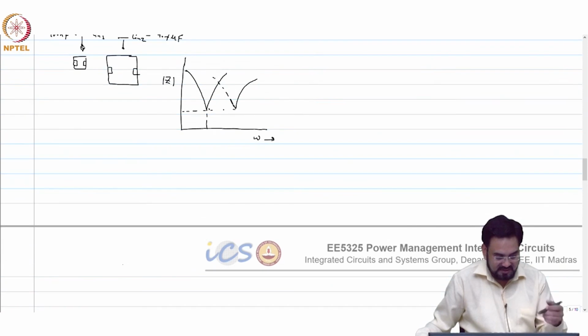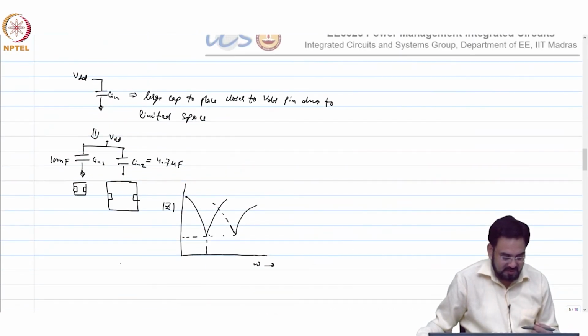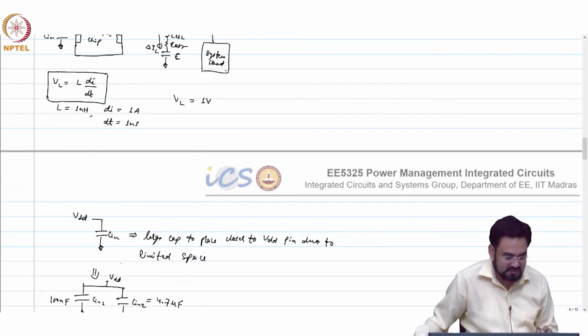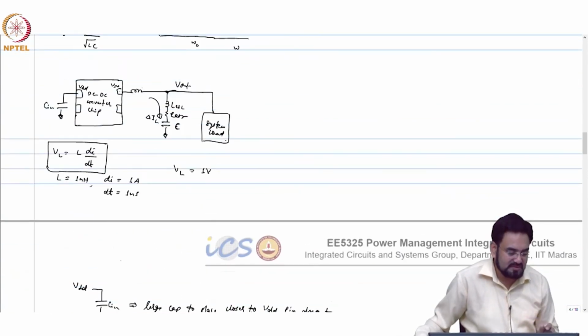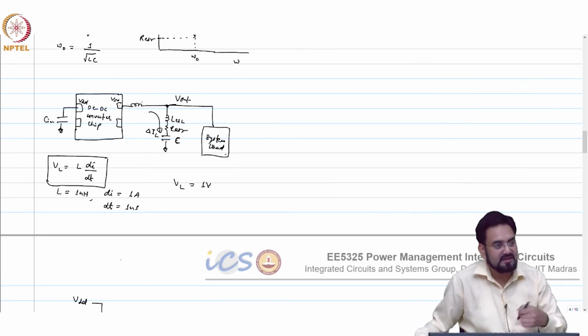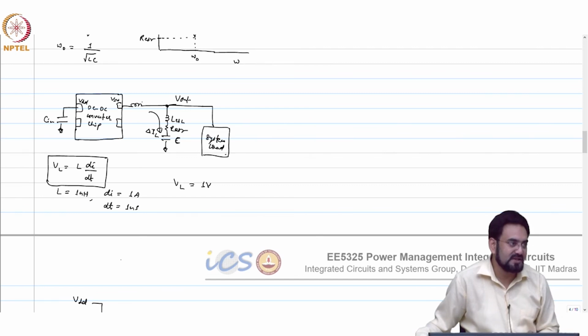Okay, so when we talk about the top level layout considerations, we will also talk about EMI and all those caused by this, because this current will be injected in. This is the VDD case, the other is the ground also, because the bottom FET is also turning on. So you care about that inductance as well.